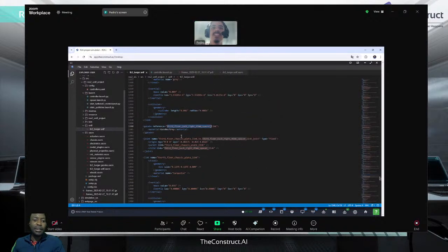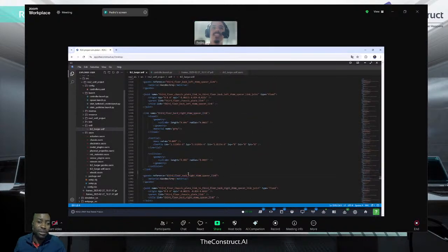So I think this just highlights how important the Xacro file can be, in cases like these where you have 4 spacers, for example, per level, or sometimes 6 or 8. If you can have code that recreates each and every one of them without having to redo everything, it would definitely help. It's good you followed the instructions that were given there, but I think this is one of the big examples of why we need to make use of Xacro files.